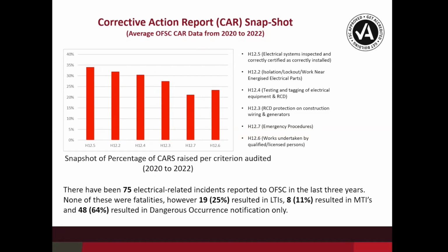So when we install temp boards, when we install site sheds and all those sorts of things, there's a certain point once we test and commission that we're required to submit. Now, we can submit a certain number of temp boards in bulk to them, and that's accepted depending on the government agency in each state. But when we get to site, we're going to look for the electrical installations that are there and the actual inspections that come with that and the records.